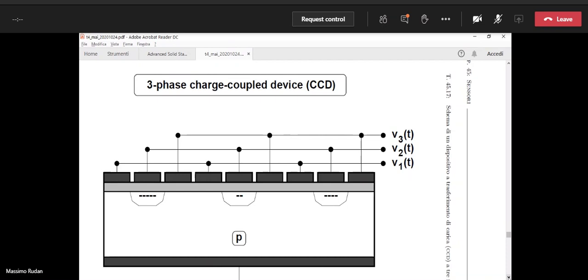But if you do not have the high voltage applied to the gate, in the positions where the voltage is corresponding to the flat band, there is no field, and the electron hole pairs that are optically generated simply diffuse away and recombine. Okay, so they do not contribute to the charge.